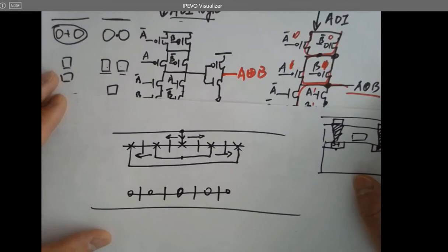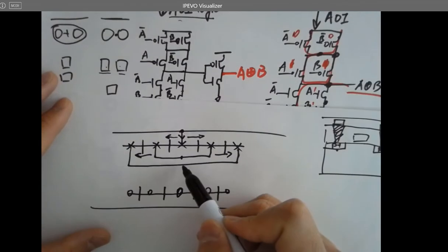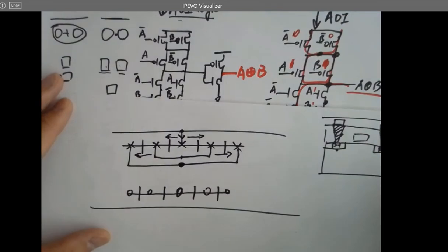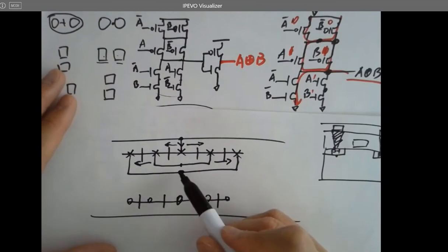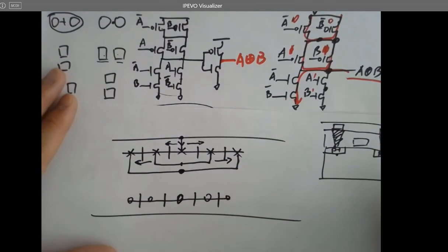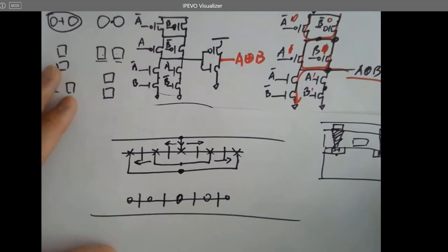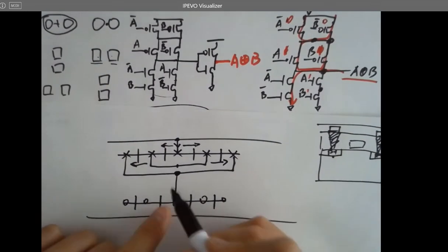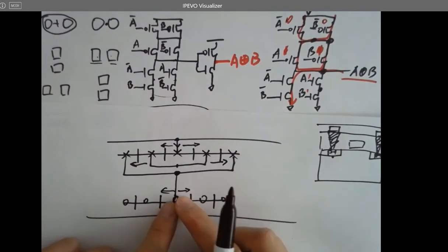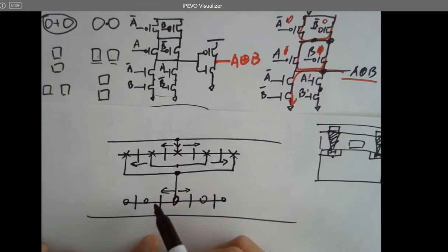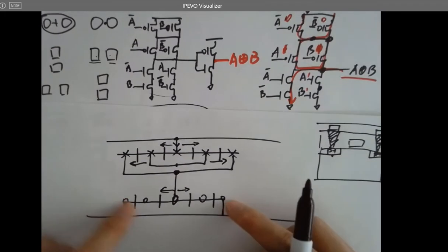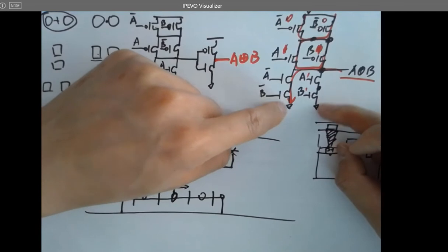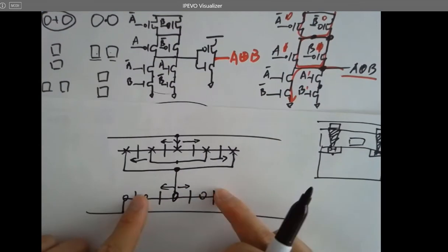All right. Where is the output from the PMOS? There? Yeah. Then you want to introduce this wire to the NMOS. So where do you want to start? I mean, you want to connect this one to where? Which is the best way to do it? Yeah, center. Because it's being split into two branches. The currents are flowing left and right, and directly go through these two NMOSes, which are in series, and then short them to the ground. Short them to the ground in series.